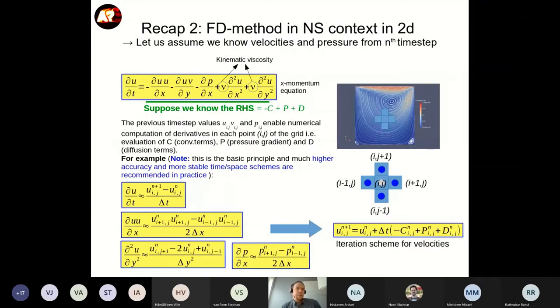Okay, the purpose over here is that, maybe I will skip this one, but if you do solve the Navier-Stokes equation, the idea can be very similar to what I just showed in the 1D example, that you need to find partial derivatives, different partial derivatives using central difference or respective formulas. You need to discretize time somehow, and in the end you want to find the solution on the next time step. So essentially what you want to find is delta u, the change in velocity, in the same way as we found d phi in the previous example.